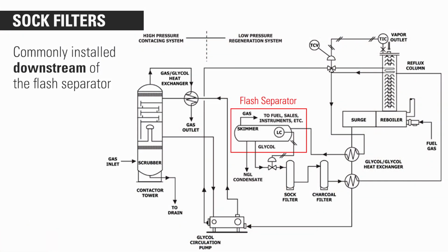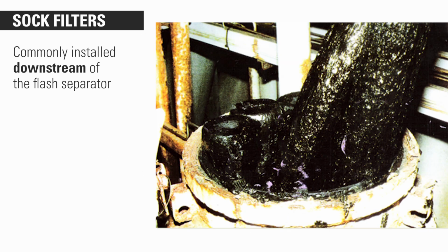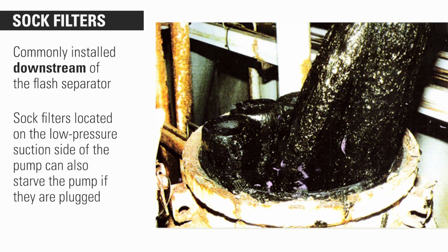If the filters are located on the high suction or high discharge side of the glycol pump, one danger is that the sock filters can disintegrate due to extreme differential pressure when it becomes plugged or clogged with debris. Sock filters located on the low pressure suction side of the pump can also starve the pump if they become plugged.